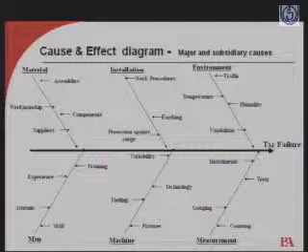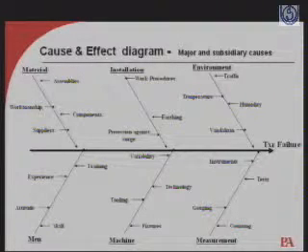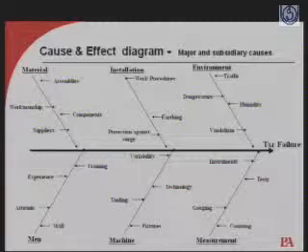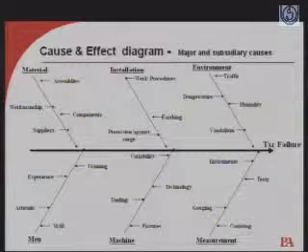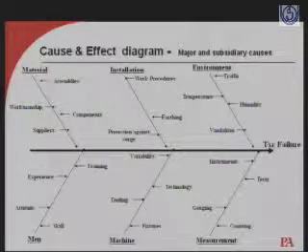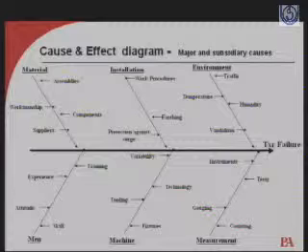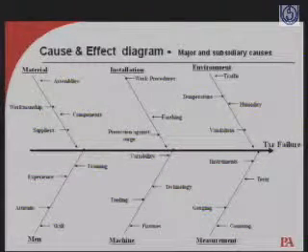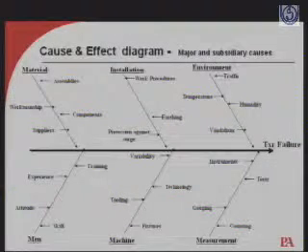Our transformer is failing quite repeatedly. Why? Is there a problem with the workmanship, or with the assemblies, or with the components, or with the suppliers? Installation, work procedures, earthing: are the transformers being provided with the right kind of protection against lightning surges? Similarly, for the environment, what kind of traffic, temperature, humidity; sometimes transformers are subjected to vandalism.